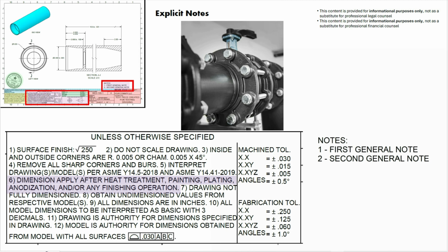Now here's a pipe flange, for example, and it looks like it has a thick coat of corrosion resistant paint on it. Just imagine if the thick paint made the through holes for these bolts so small that the bolts wouldn't fit through. What would happen next is someone would go and drill them out, damage the paint, and create a position where corrosion can start again because the paint is missing. So you want to prevent that from happening in the first place, and it's explicitly called out in the drawing.